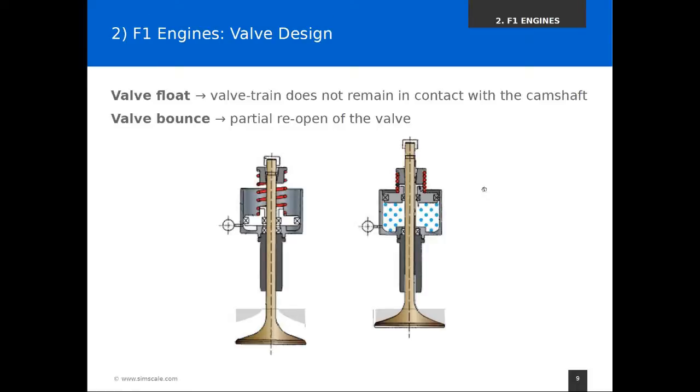And this is also a very bad operating condition for an internal combustion engine, because that means that the valve is not tight anymore and you have very high dynamic loads and very high stresses, and this is going to kill your engine very quickly. So these 2 conditions are something that we definitely don't want to have, and in a bit we'll see how to find this out using simulation.